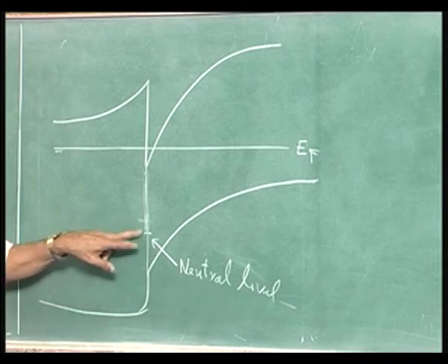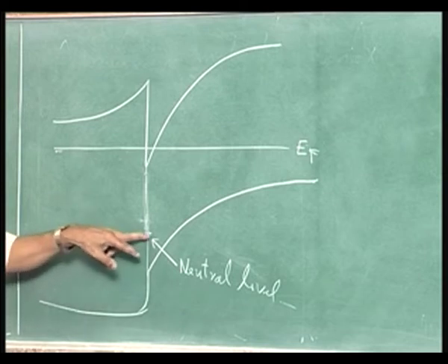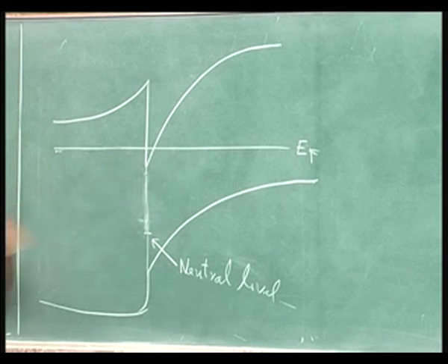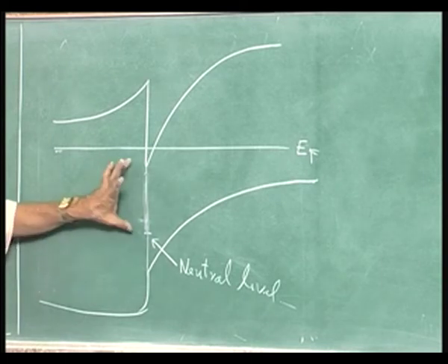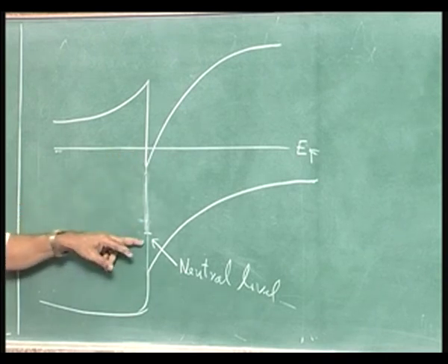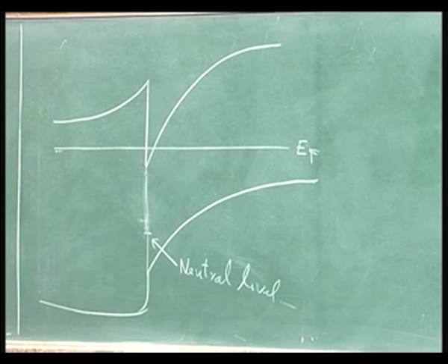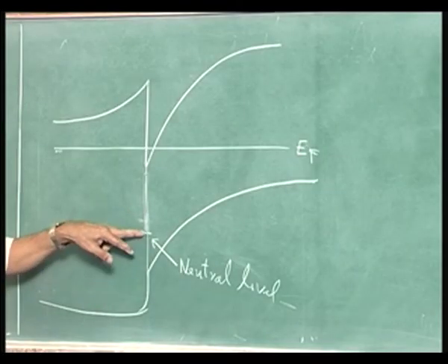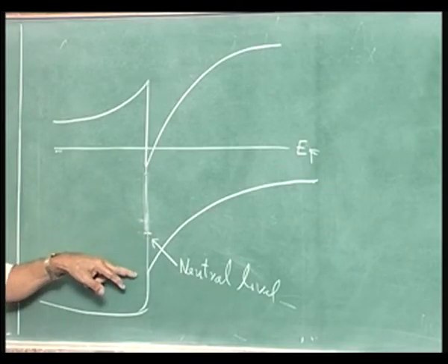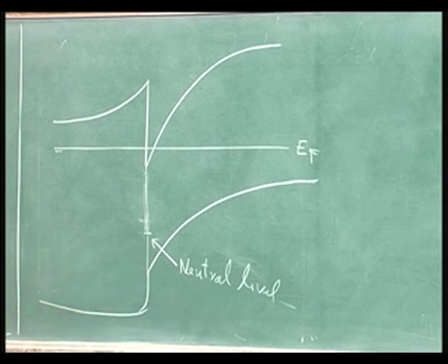Okay. So, what is the situation if they are perfectly aligned? Charge on this aluminum gallium arsenide at the interface is given by what is this gap? They are acceptors, DIT multiplied by that energy gap, and all these acceptors are above the neutral level and they are below the Fermi level. That means they are occupied. When they are occupied, they are negatively charged. Below the neutral level, they are donors. They are occupied. They are neutral. So, that is perfect. I hope you are able to understand that.